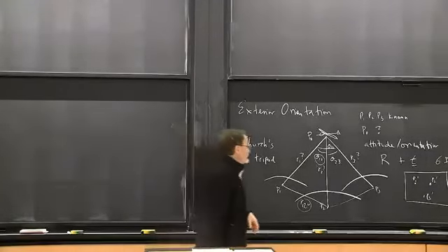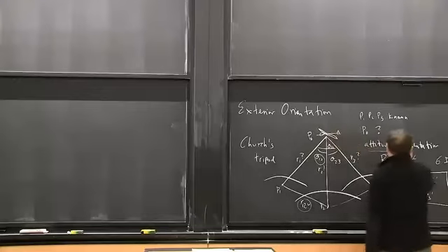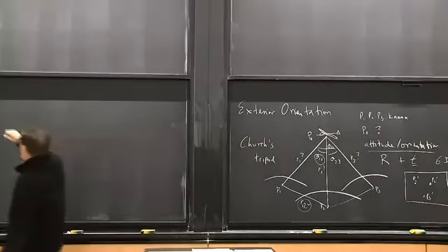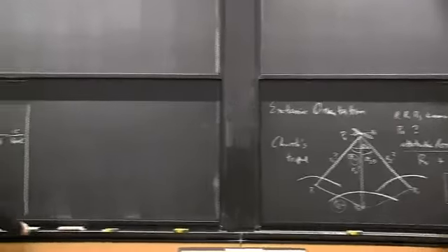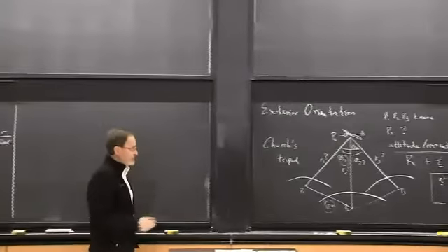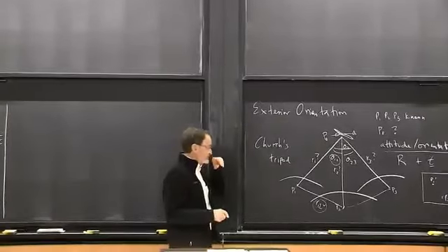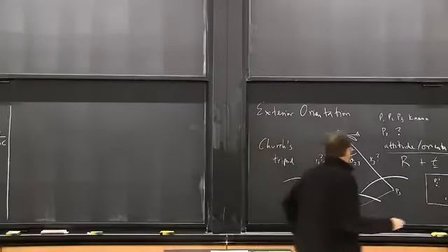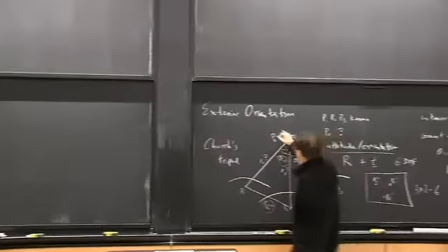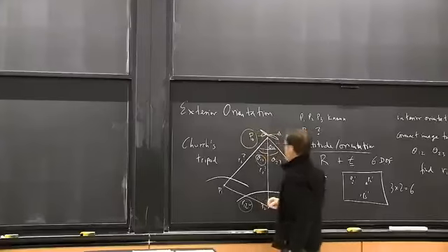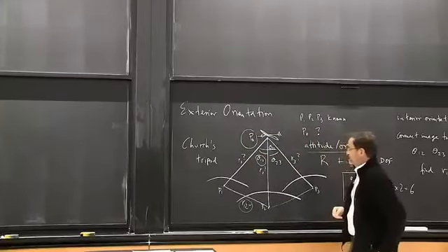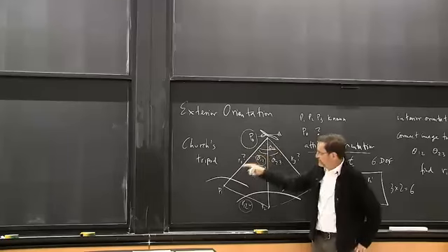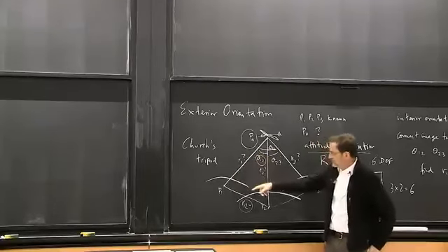So what's left? Well, what's left is finding the attitude. And what is attitude? Well, it's the orientation relative to the ground coordinate system. So there's a rotation we need to find. Well, the thing is that once we know where the plane is, the center of projection P0, then we can construct these vectors in 3D in the ground coordinate system.